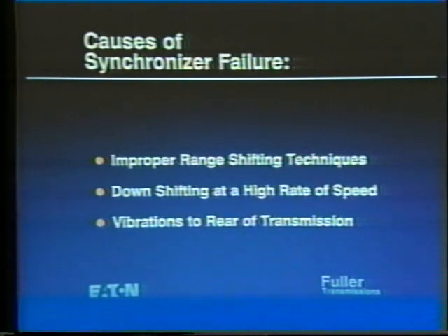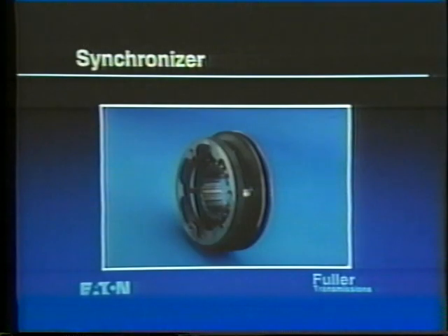Synchronizers fail due to improper range shifting techniques, such as range shifting in neutral, downshifting at a high rate of speed, and vibrations to the rear of the transmission. There is a friction material on the surfaces of Fuller synchronizers which has greater wear resistance than bronze synchronizers.